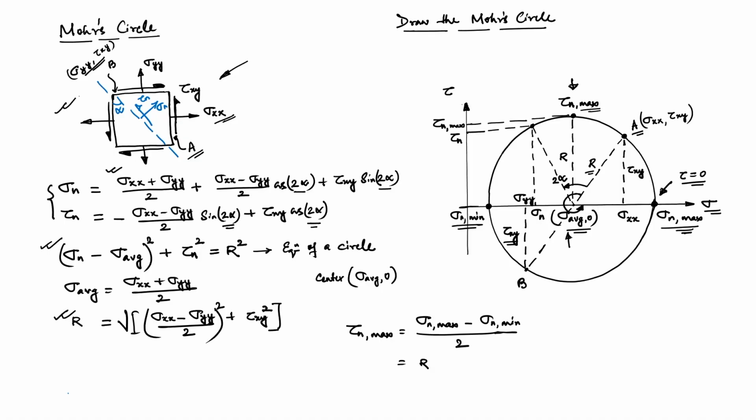It is very easy to get that from the Mohr circle, otherwise you have to derive all these quantities and then see. Here it is clearly visible that the principal plane is exactly on the sigma axis, and hence tau is equal to 0, which is not the case for a plane where shear stress is maximum. There we have a finite value of the axial stress.